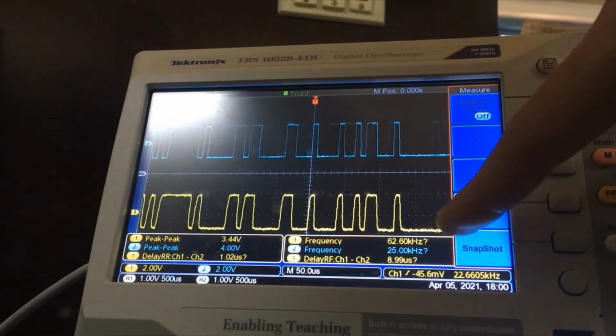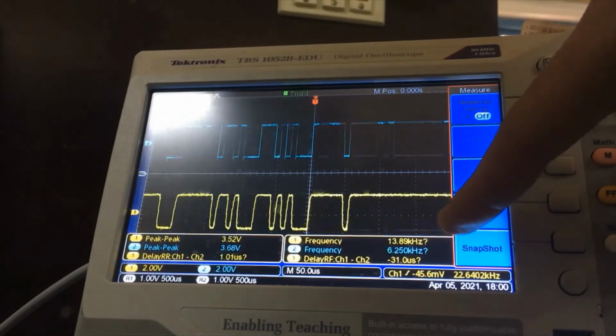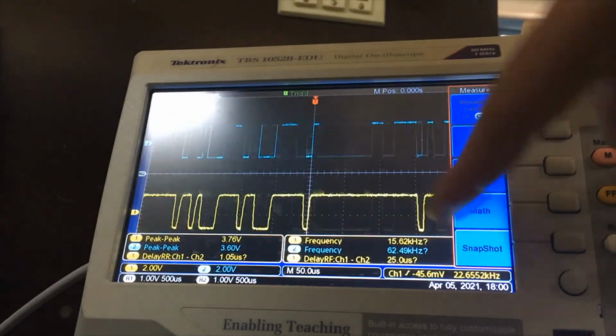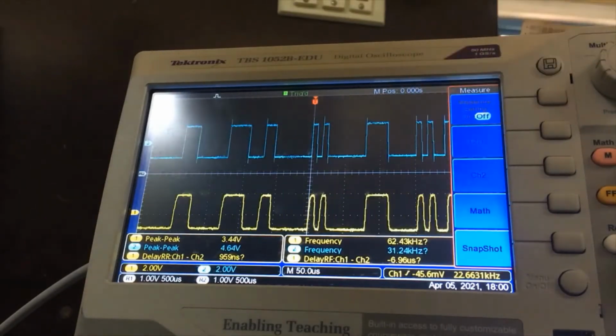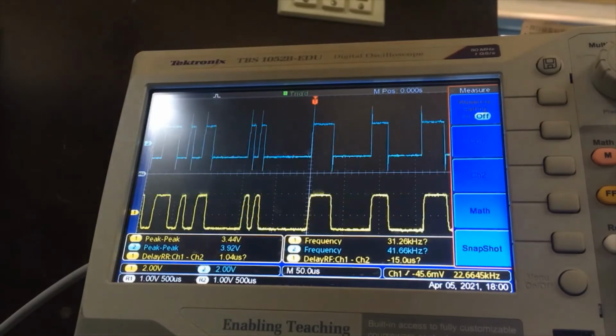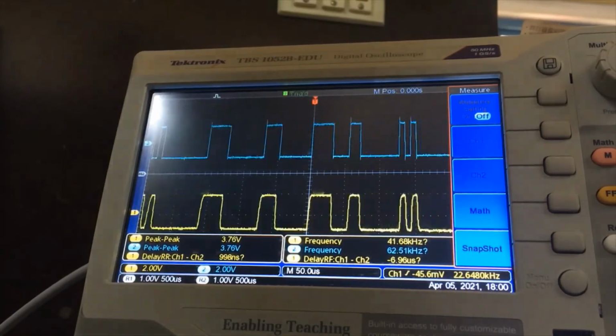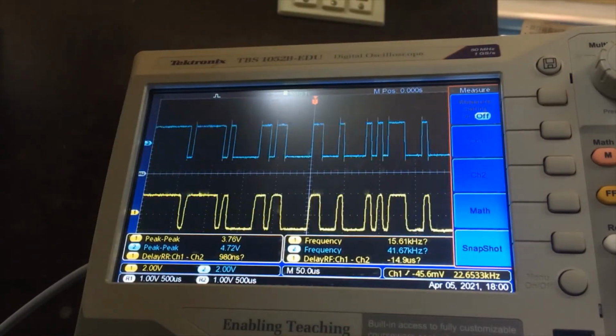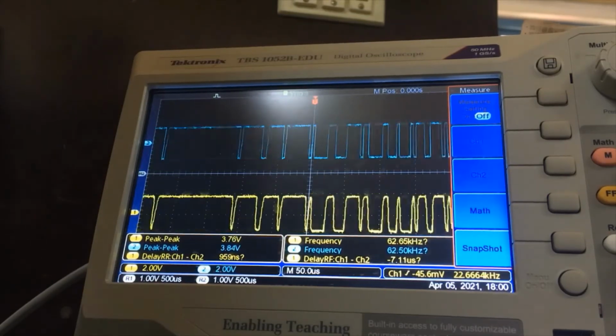The channel is acting as a low pass filter, which will not allow higher frequencies to pass. Right now the sampling frequency I have set to 16 kilohertz. What I can do is increase the data rate or the line speed correspondingly. Let us first see the basic 4 kilohertz.